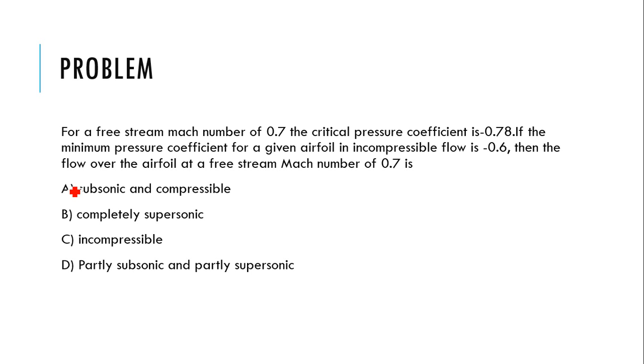Please just guess the answer. What will be the correct answer? So partially subsonic and partially supersonic. How is it partially subsonic and partially supersonic? Like they have given the critical pressure coefficient. That means somewhere on the wing, the Mach number at subsonic will turn into supersonic.